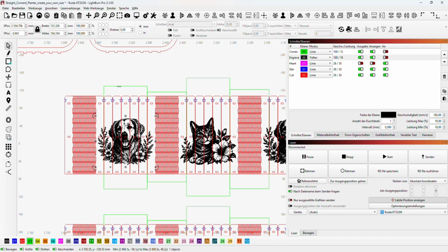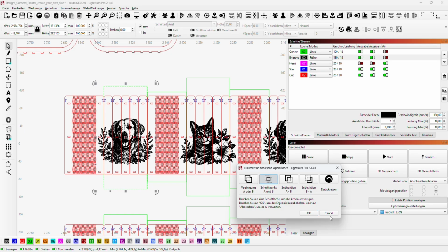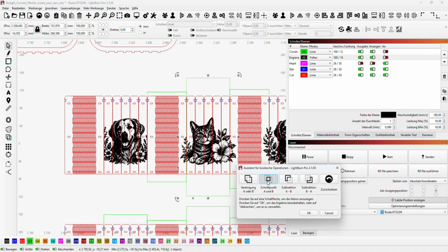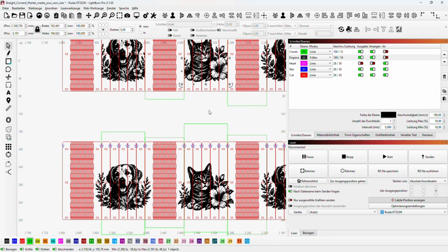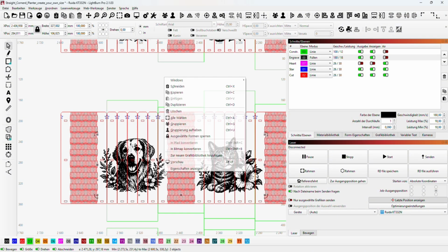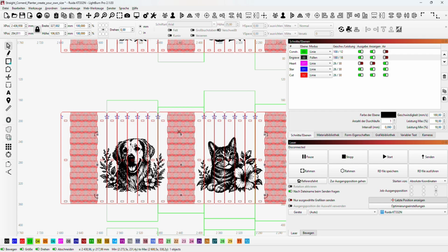First, select the engraving. Then, while holding Ctrl, select the rectangular cutting template. Finally, use the Boolean AB tool to split the design. For the corner piece, group both engraving sections first before applying the Boolean operation.